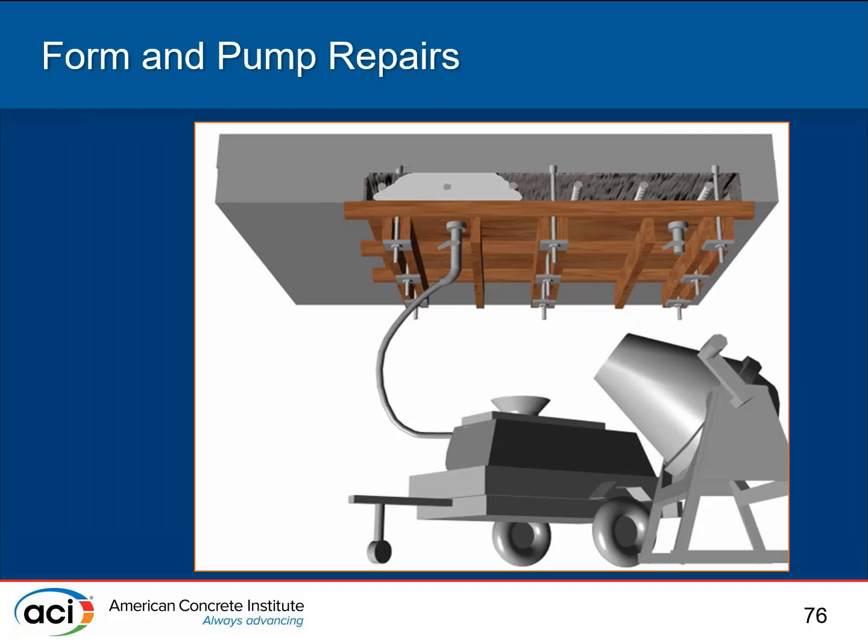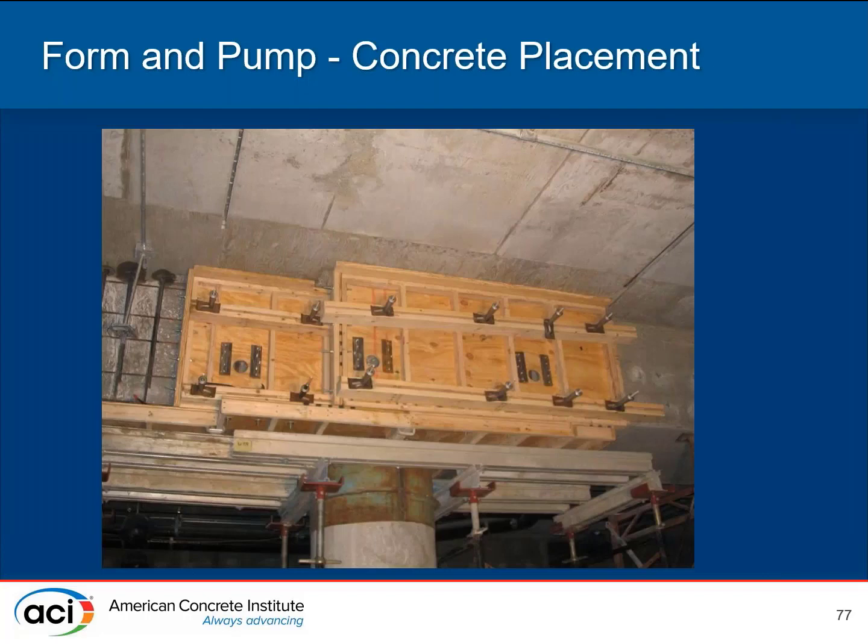So you often see this in a congested area, a congested structure, lots of steel going on. Biggest difference, the pumping equipment. You need a lot higher pressure than your normal pump. It's not a normal concrete pump. And then also the formwork needs to be designed for the pressures. So you often see the formwork, as you can see here, a lot stouter than you would normally get. Given the size of this, that's some pretty stout formwork we have here.